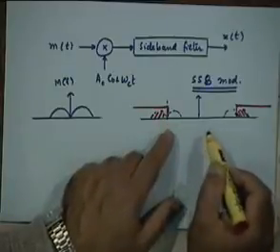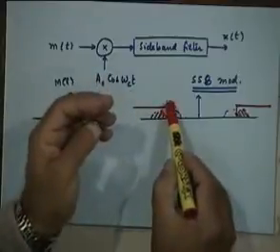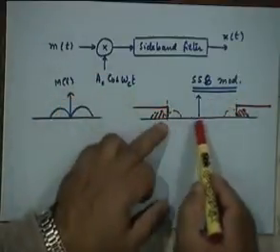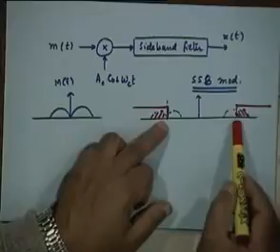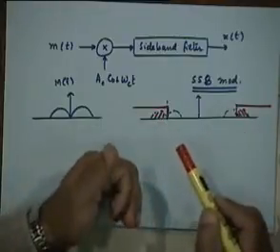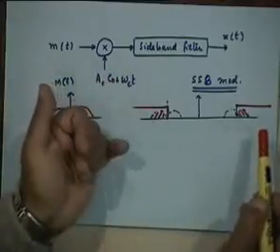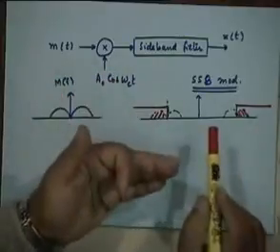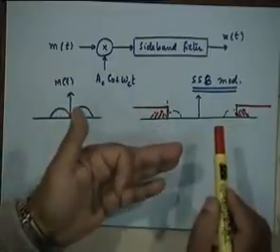If you want the lower sideband, you should have a low pass filter with a cutoff frequency of f_c, right? So depending on whether you want the lower sideband or the upper sideband, you can use an appropriate filter, which ideally could be either high pass or low pass.